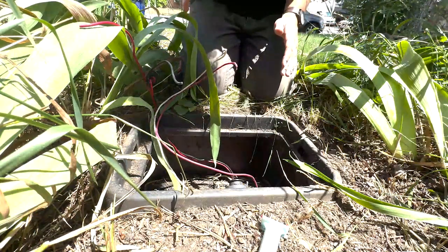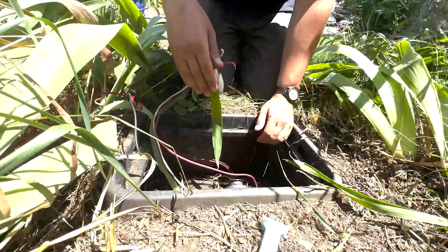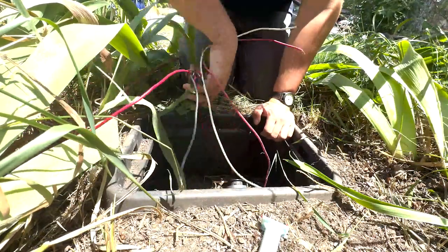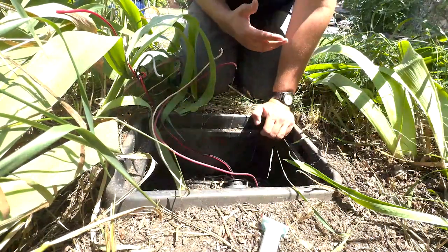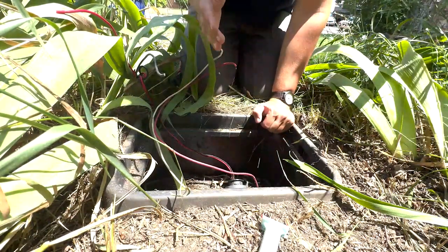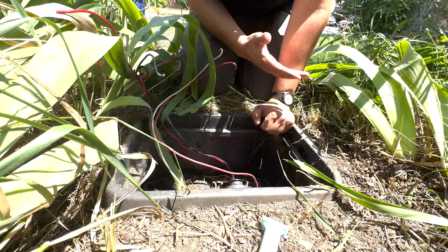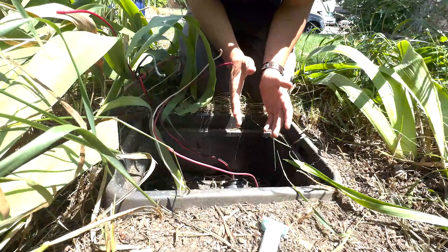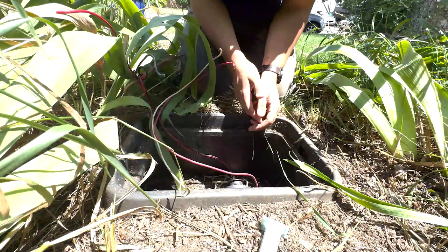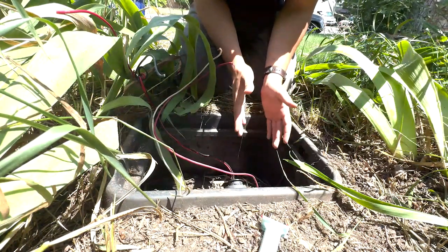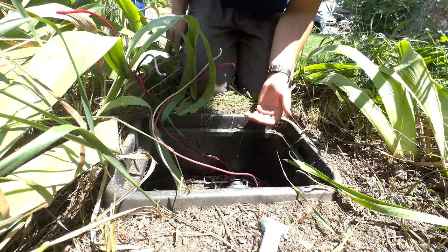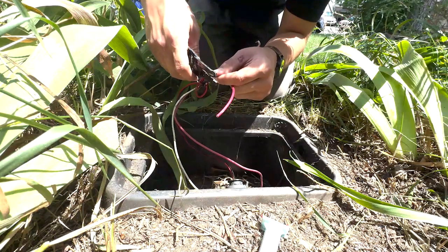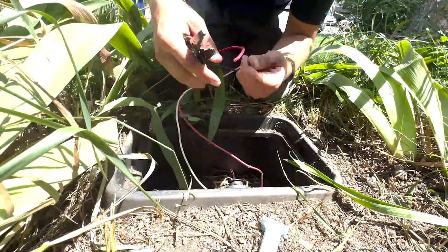Now, the only thing that leaves is our flow sensor. And what I normally do when I conclude that the problem is the flow sensor is I check the wires on the flow sensor to make sure there are no nicks, and then I'll go replace the body of the flow sensor to see if I can get another flow sensor to read the flow data coming through this pipe. Now that we've broken down all 3 places where there could be a problem in your flow loop, troubleshooting your flow loop should be super easy. Now, all we have to do to finish this project up is strip the wires coming from our flow sensor and put wire nuts back on everything that we took wire nuts off of.